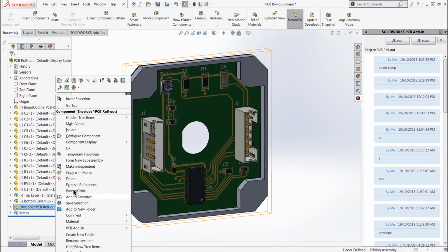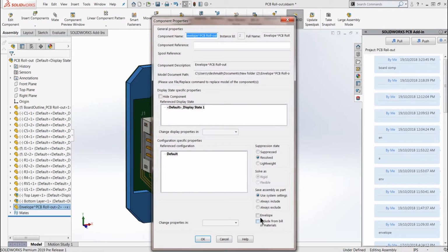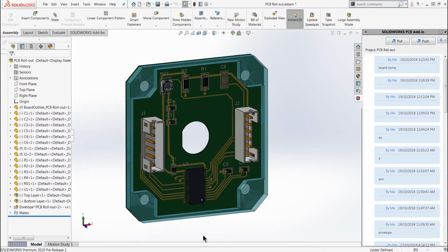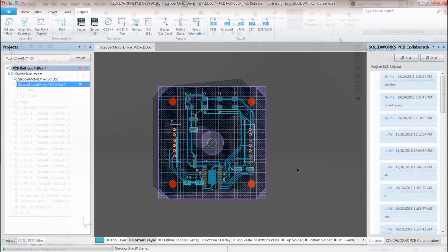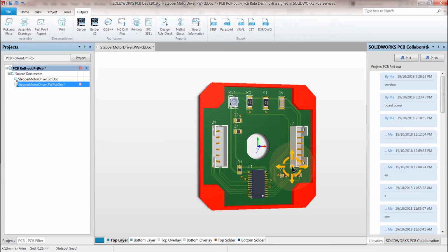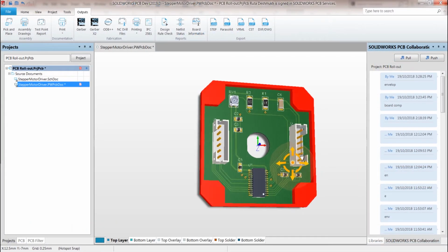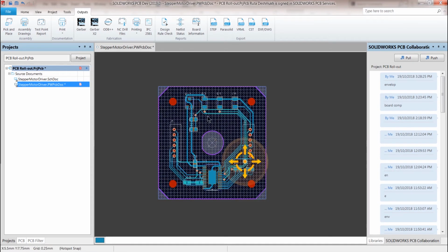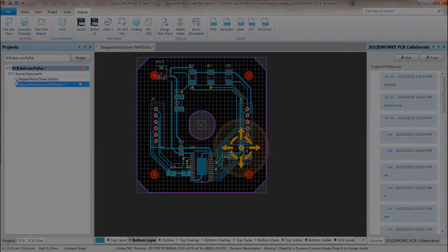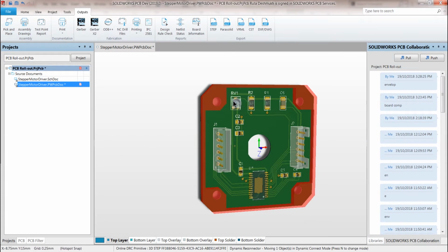For example, you can add a surface restriction using the component envelope, and this will be reflected back on the PCB as marked in the color red, and the affected components are also highlighted in red for not passing the collision design rules. Thus, you can easily place a board in a tight enclosure.